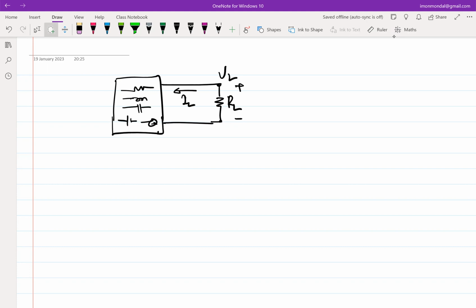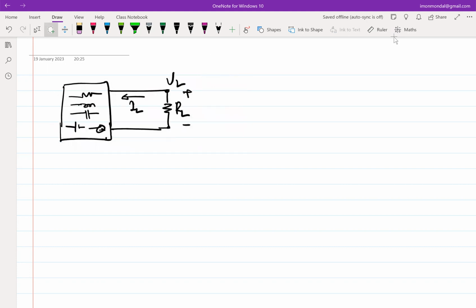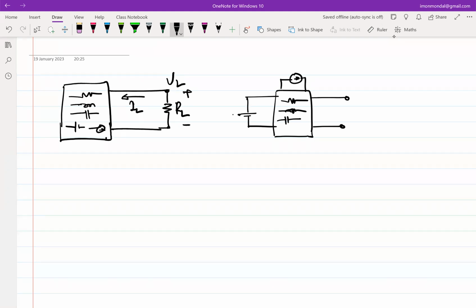I can figure out this voltage obviously by solving the KVL, KCL of the entire network. Alternatively, I can do an experiment, rather 2 experiments. In one experiment, I'll open this RL, and this network remains as is. Let me take out these voltage and current sources because that will help make the point. Nothing has changed, but essentially I've taken them out to make a point. So this VL will be the sum of 2 voltages obtained in the following manner.